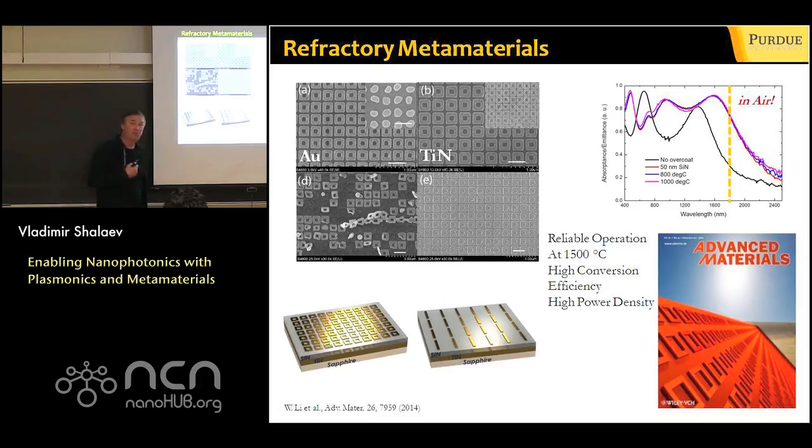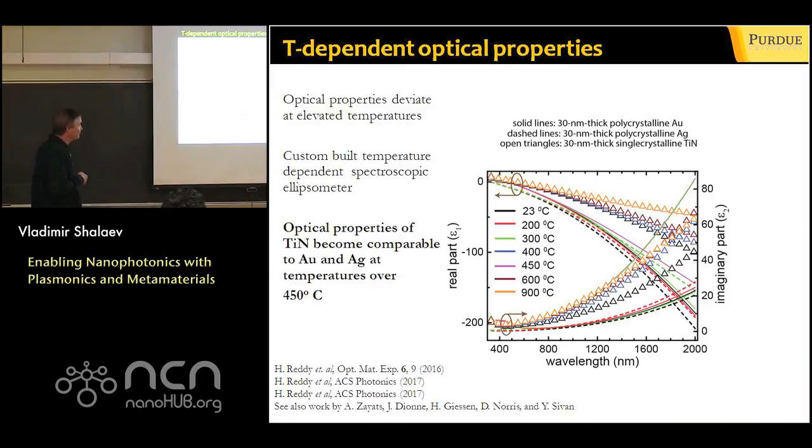From the point of view of ideas, it was known that with plasmonics you could make these frequency selective emitters by putting in this type of antennas. But what was lacking was a material which you could heat up to these high temperatures for thermophotovoltaics, since the higher the temperature, the higher the efficiency. And with conventional plasmonics, you're really limited in that regard. But with these refractory plasmonic materials, it makes a big difference.